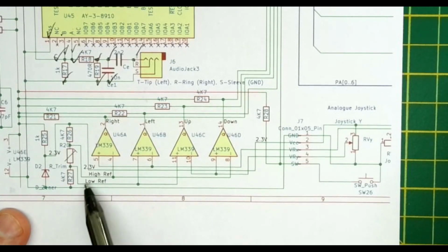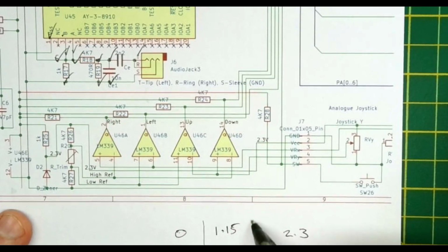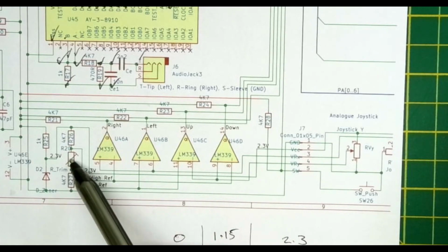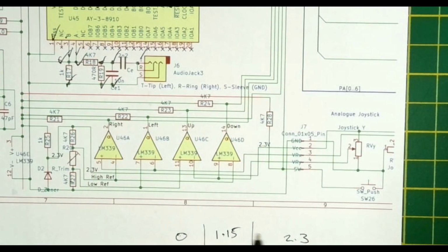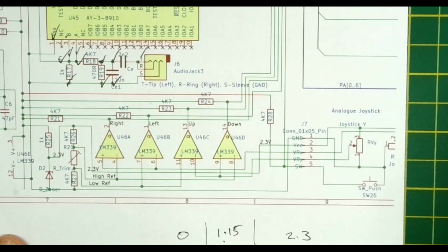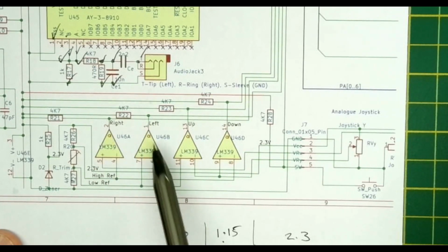We also need to produce a low reference and a high reference, so we need 2 voltages. If we've got 0 to 2.3 volts, and the middle is about 1.15 volts, then we want a voltage either side, where if it goes below that or above that, we say the switch is on. This little circuit is a 4.7k trimmer, a 4.7k resistor, and another 4.7k, and we can adjust the trimmer to make this bit wider or narrower. That trimmer allows the voltages to come closer to the midpoint or further away. This produces the low reference down here, and this is the high reference, and these feed the comparator signals to give us an output for the right, the left, the up and the down.